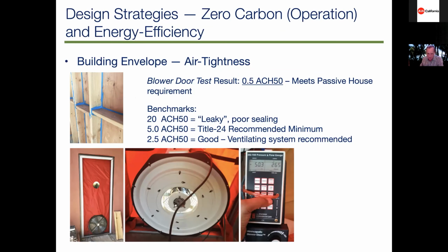He trained his contractor basically on this job, and he did achieve the passive house certification, half an air change per hour at 50 pascals pressure, very tight house.